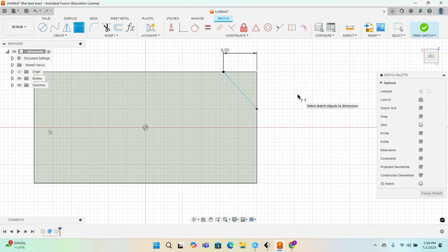Now I'm going to go over how I do this again. I'm going to click once and let go. And I'm going to come down to this point and click a second time. And then I'm going to drag out my mouse and click a third time. When I click a third time, it opens up that window. And instead of telling me how long the line is, it moves it so that the point of that line is at that specific location. Notice the line is now turned black. It is fully defined.